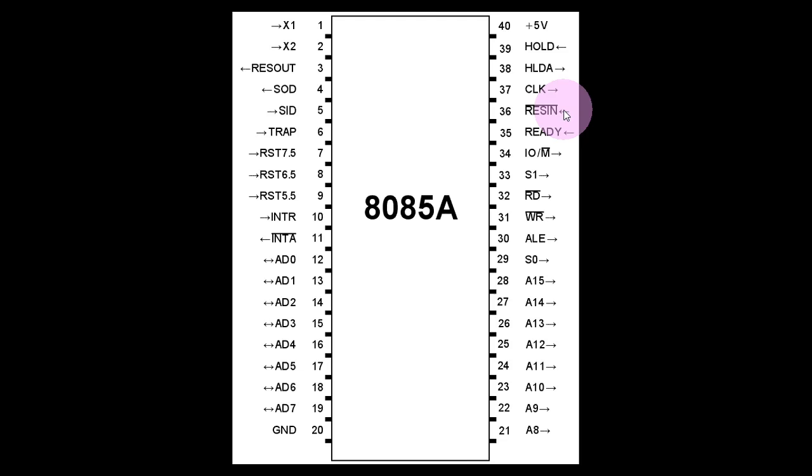Now, that 64 kilobyte memory should have every location of 8 bits. You cannot have a 64 kilobyte memory in which every location is of 16 bits or 32 bits. No, you have to have a 64 kilobyte memory where every location is of 8 bits, because that is the kind of memory this 8085 processor is expecting. And where is it connected? That memory has to be connected.